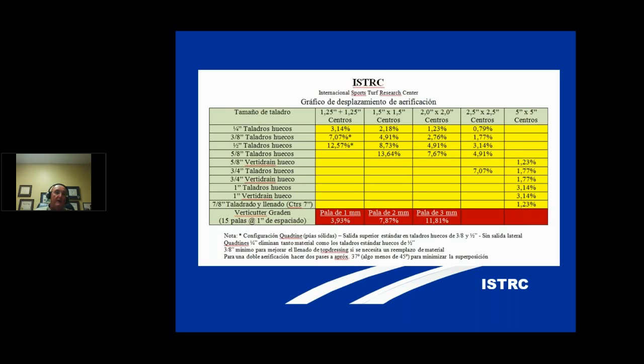I've had situations where a good 200 millimeters an hour was going through the top, and it drops down to the 10 inches at the 200 to 300 millimeter depth. Then it makes sense to do a deep drill. Why not a Verti-Drain? Because the Verti-Drain is really only effective from 8 to 10 inches deep. It takes a drill to get down to the 12th inch to open it up completely. And you can also do a drill and fill, where it can actually pour the material in. Or you can do it yourself.